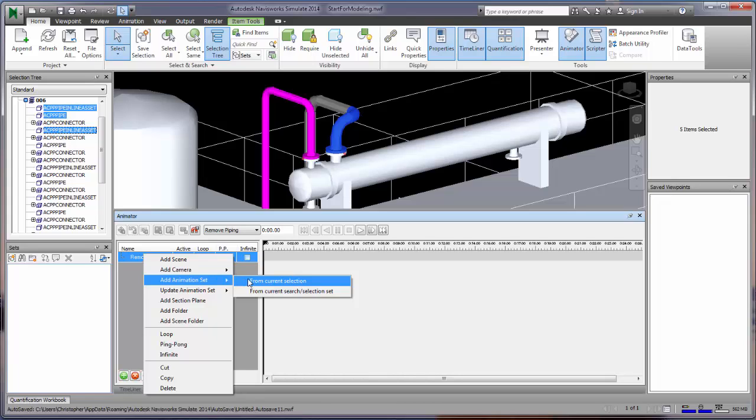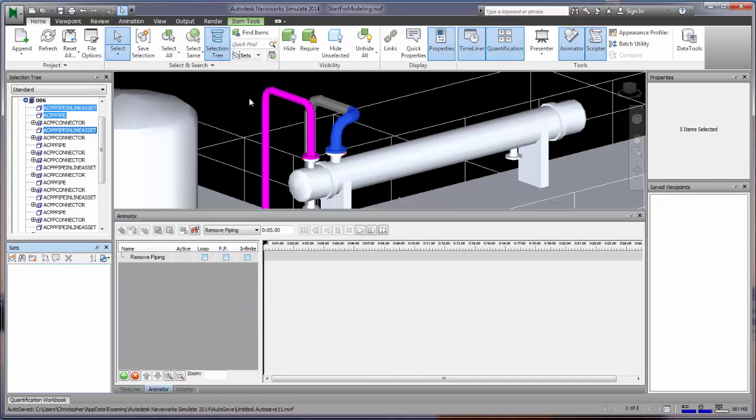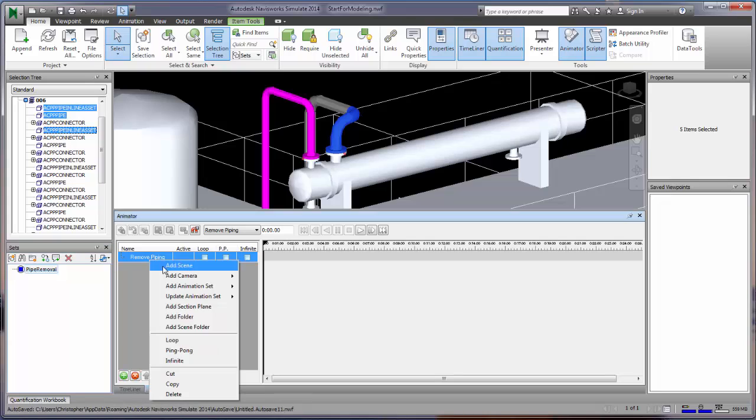I can also create selection sets over here, and I would do that from the dialog box up here, and I could manage the sets. I could save the set, and this is pipe removable. And so when I select another one, and then when I select it, it's automatically going to select that selection set. And so I'm just going to use the selection set.